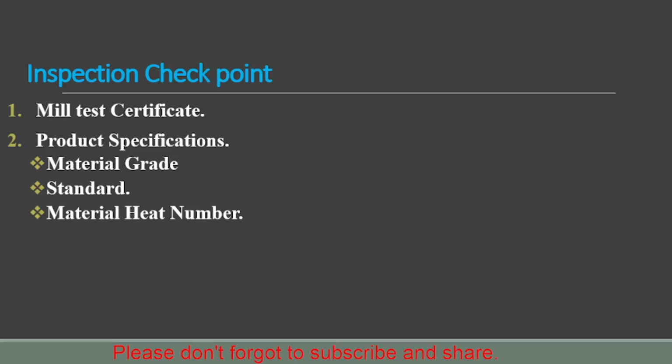There is the heat number or lot number. This heat number and lot number must tally with the material certificate. Then we will be able to understand that this material belongs to this material certificate.